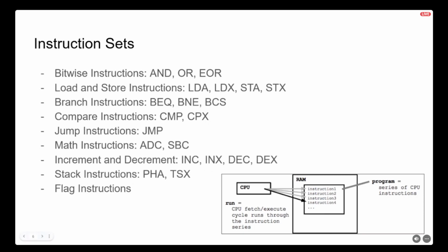You can also call instructions on the stack, which again is a form of memory. PHA, meaning to push your accumulator onto the stack. TSX, transfer stack pointer to X, the X register. A lot of these instructions do get kind of repetitive.